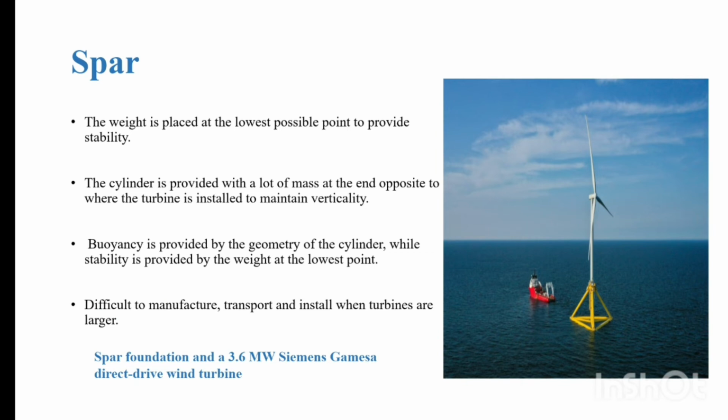In short, buoyancy is provided by the geometry of the cylinder, while stability is provided by the weight at the lowest point. As turbines become larger and larger, it requires very long cylinders to compensate for the weights, which makes this solution very difficult to manufacture, transport and install.